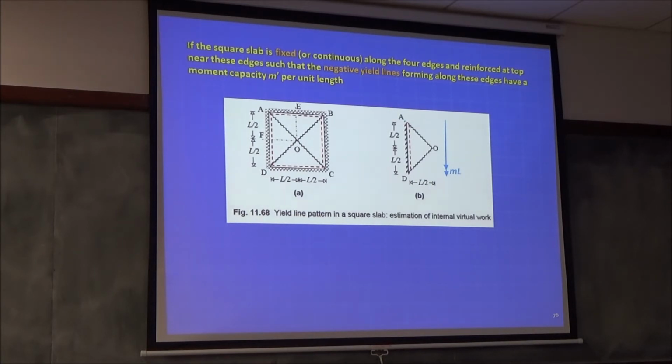Will it be pointing down or up? In other words, will it add to the internal work or subtract? It will add. By the way, all internal work is positive. And you should know that if you have a beam, the sagging moment will be anti-clockwise and the hogging moment will be clockwise, but both will be in the same direction. Am I right? So you should intelligently mark it like this. Anti-clockwise, hogging, but they actually are pointing vectorially in the same direction.